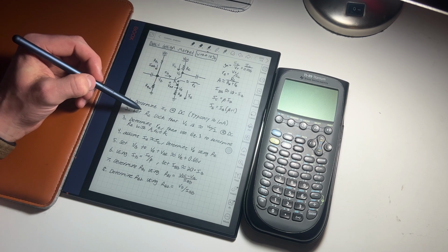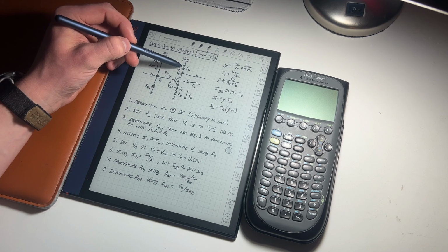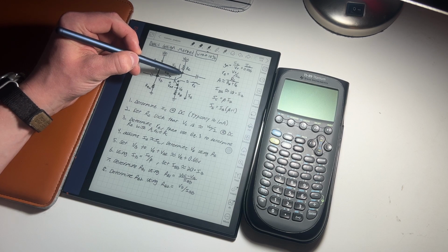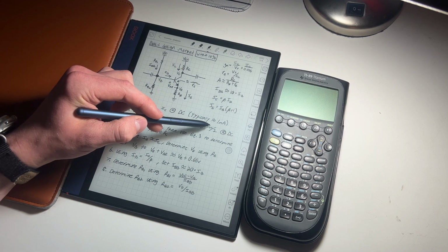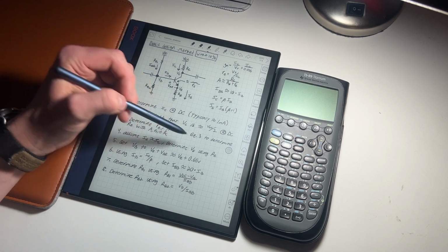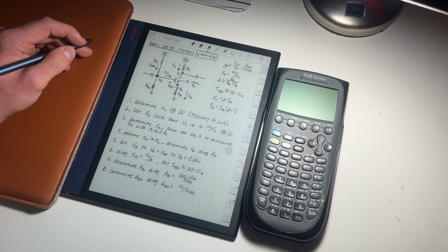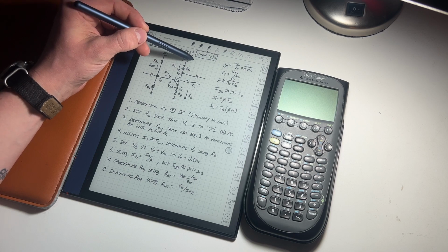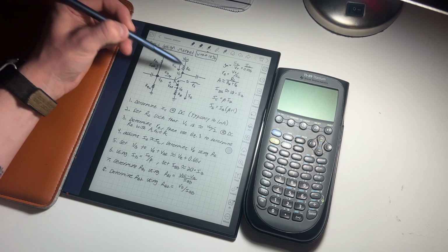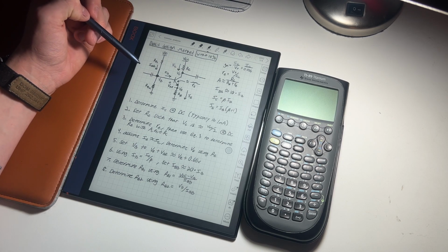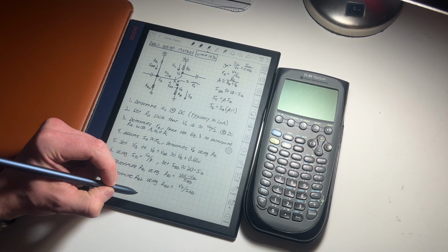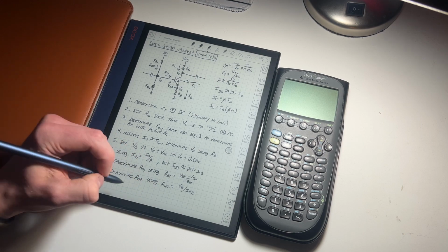Next, set RC, this resistor here, such that VC, which is the voltage at the collector, is around your supply voltage divided by 2 at DC. So, if I have a supply voltage of 5 volts, I want VC to be around 2.5 volts. And what this is going to allow me to do is get the maximum swing of my output voltage.